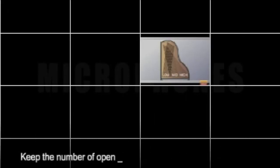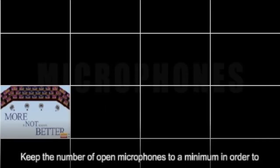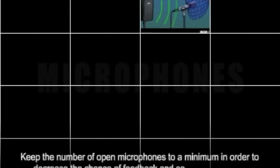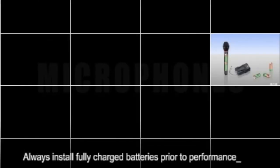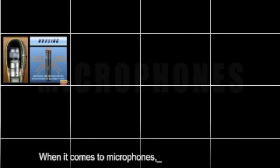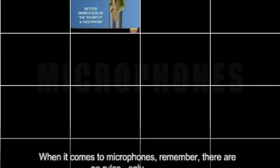Keep the number of open microphones to a minimum in order to decrease the chance of feedback and sound degradation. Perform a thorough frequency scan prior to selecting a wireless system channel. Always install fully charged batteries prior to performance time. When it comes to microphones, remember, there are no rules, only guidelines.